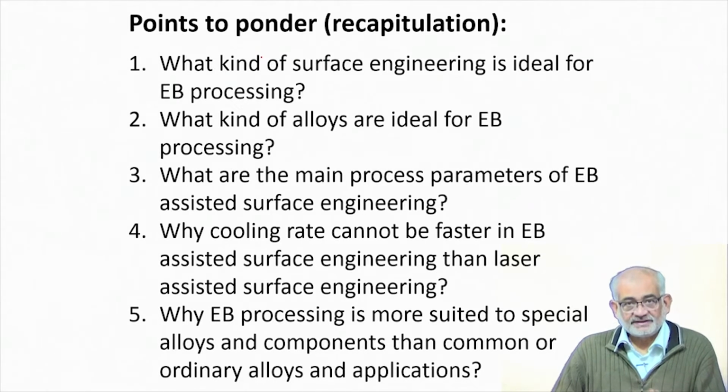But EB is not necessarily an ideal tool for surface engineering. Why is this still used for surface engineering? Because if you want to clad or harden or deposit or simply surface melt a very sophisticated and a very reactive metallic component, then the high vacuum that you have in case of electron beam is very, very helpful.